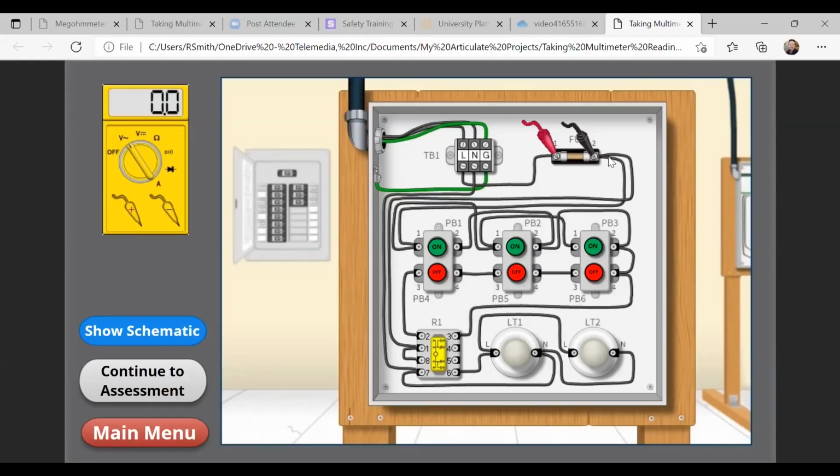So that's the real thing we're measuring, potential difference. So did the electrical energy we're seeing inside of these wires, that push for the electricity, change from this side of the fuse to this side of the fuse? And the answer is no, it's been just as live and high potential from inside to outside of the fuse. So the difference between high potential on this side and high potential on the other side, the difference between those two potentials is 0 because they're both high potential.